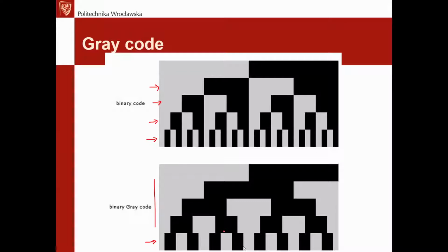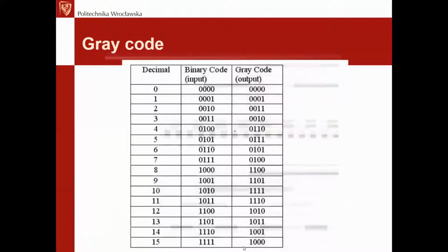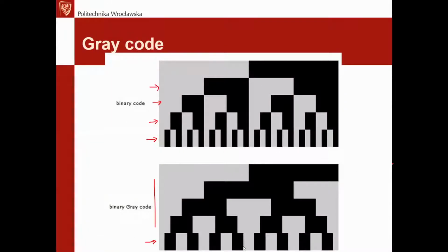It's a great gain because it's just about reading back. So instead of reading this way, we are reading this way. That's simple. We just need slightly different logic, but that's not a problem. We gain a lot in frequency readout, in frequency characteristics or required parameters of the electronic path. That's the major reason why the gray code is used extensively in various encoders, everywhere, because of this reason.